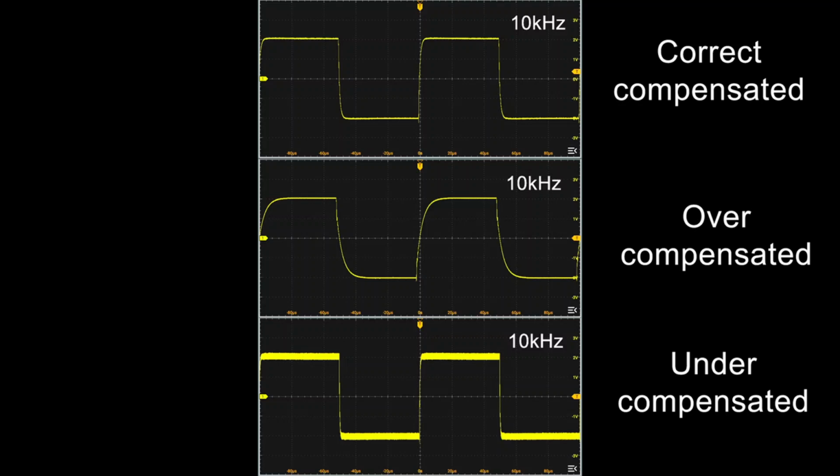These 3 waveforms may suggest to us that there is a way to determine the correct values for the compensation capacitors. First, we start with using high-value compensation capacitors, so that the amplifier is overcompensated. Therefore, the amplifier produces output square waveforms with severely rounded rising edge and falling edge. Then we reduce the capacitances until oscillations begin. At this point, stop and increase the capacitances slightly until all oscillations disappear. Now the values of these compensation capacitors represent the correct compensation to be used by the amplifier.